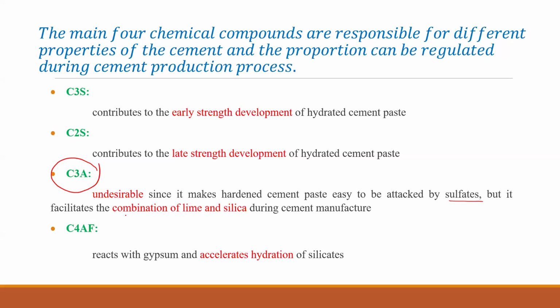But it will facilitate combination of the lime and silica during the cement manufacturing. So it has an advantage as well during the cement manufacturing process. C4AF reacts with gypsum and accelerates the hydration of silicates.